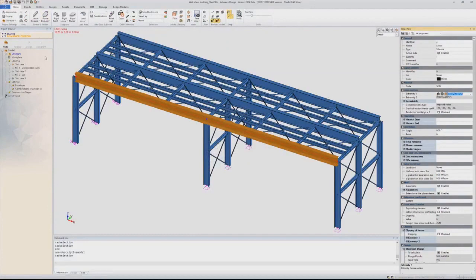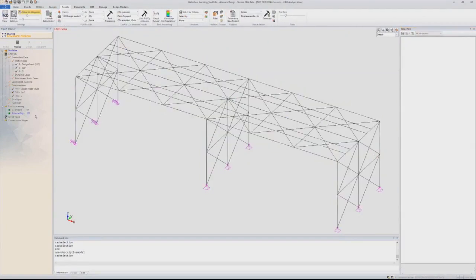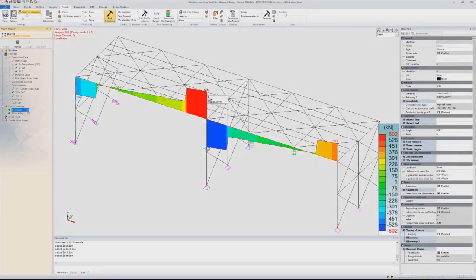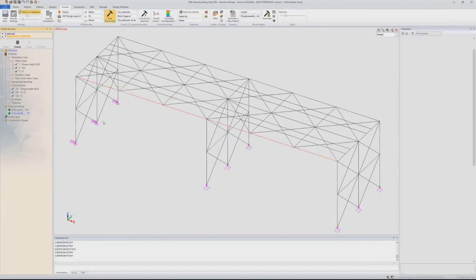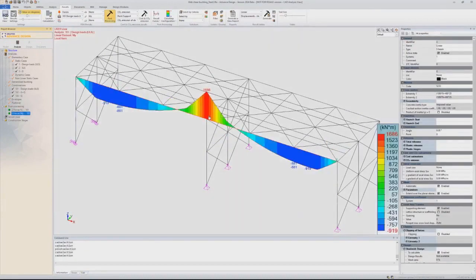If I just run the finite element calculation just to check the internal forces first, I would get some shear force diagram with a peak shear force on the middle support, but I've also got some bending moment there, so maybe the flanges won't be able to contribute.